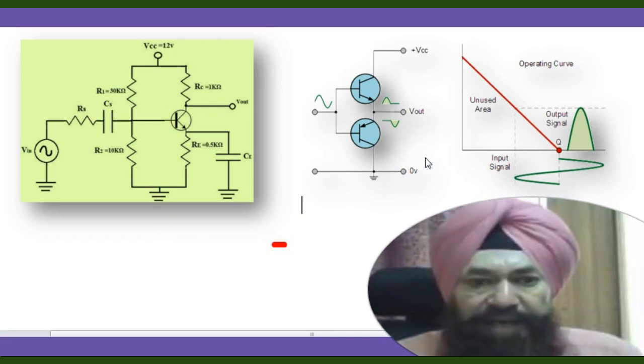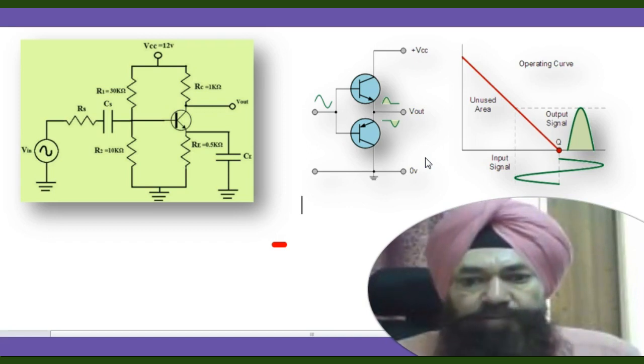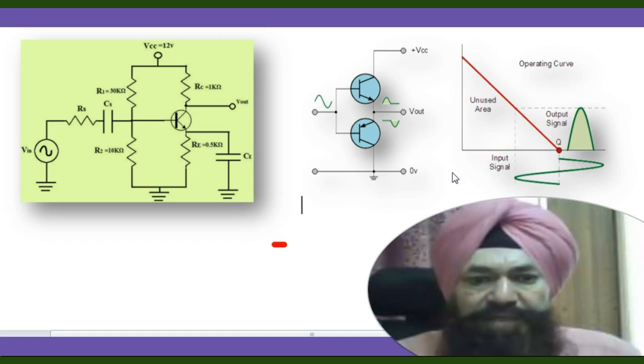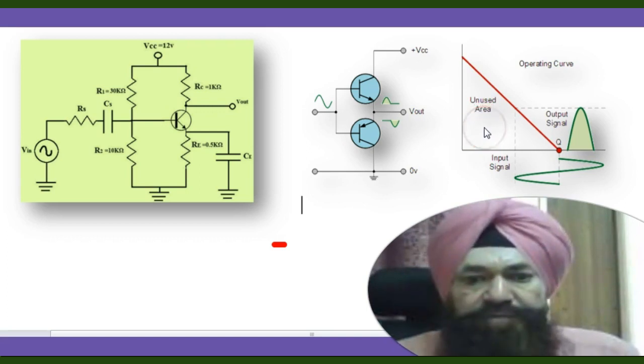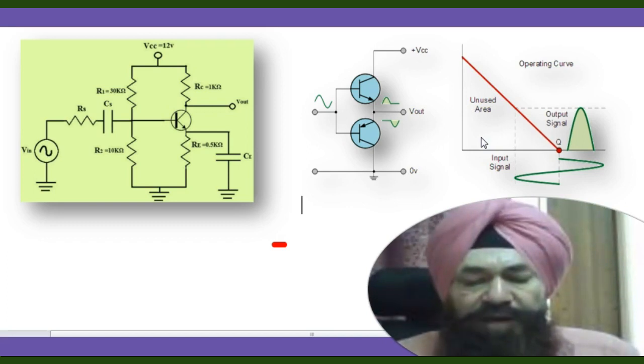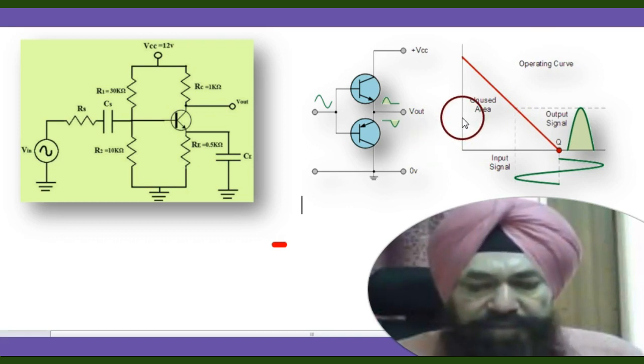Large signal amplifiers are designed to provide a large amount of AC output power so that they can operate output devices like speakers. The main concerns of the large signal or power amplifier are the circuit's power efficiency, the maximum amount of power the circuit is capable of handling, and the impedance matching to the output device. It may be noted that not all large signal amplifiers are necessarily power amplifiers, but it is safe to say that most are. This type of amplifier is termed the power amplifier.